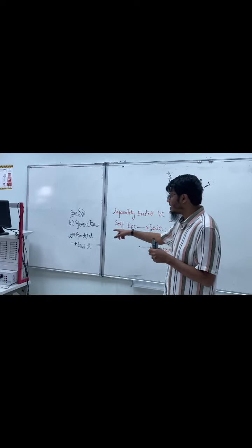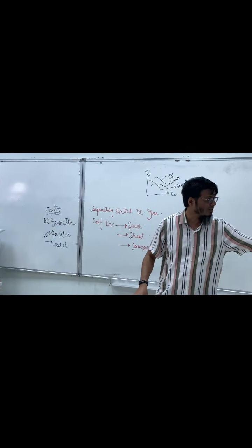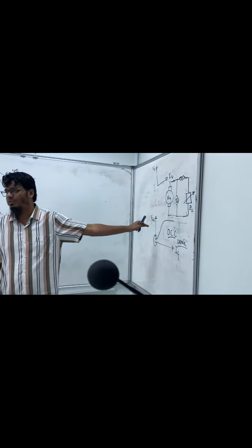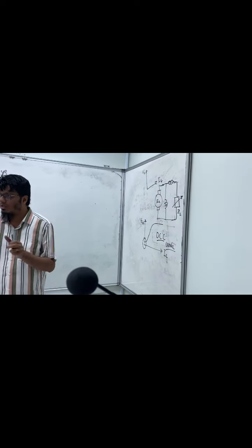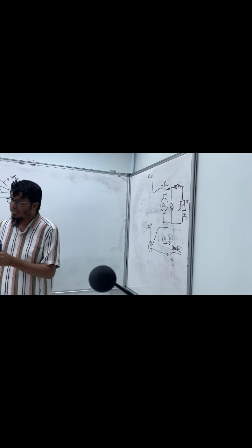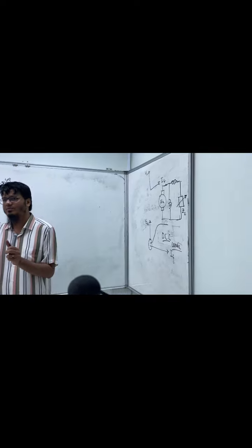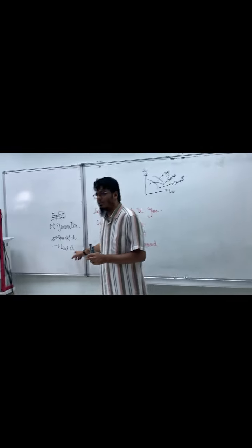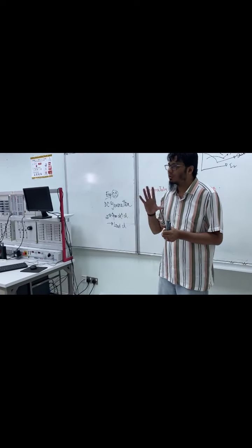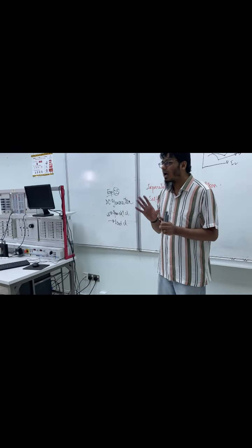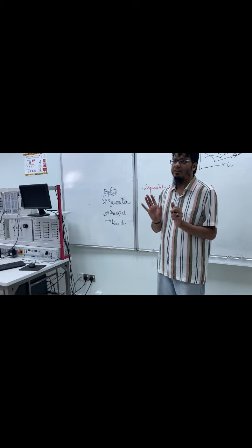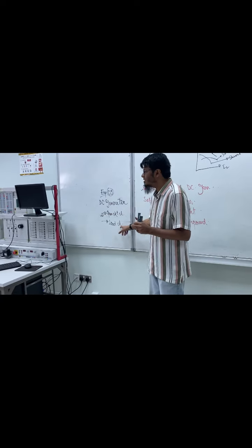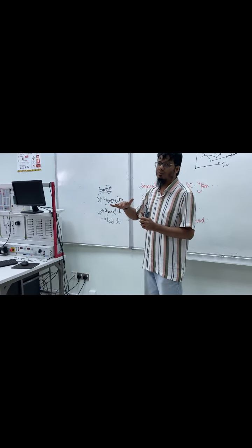And what is the open circuit characteristics? This is field current versus open circuit voltage. So we keep the load side open, we change the field, and we see how it behaves. Clear? Yes. Okay. Second objective, load characteristics. We will see how the change of load behaves for different types of generators. The load characteristics is load voltage versus load current.